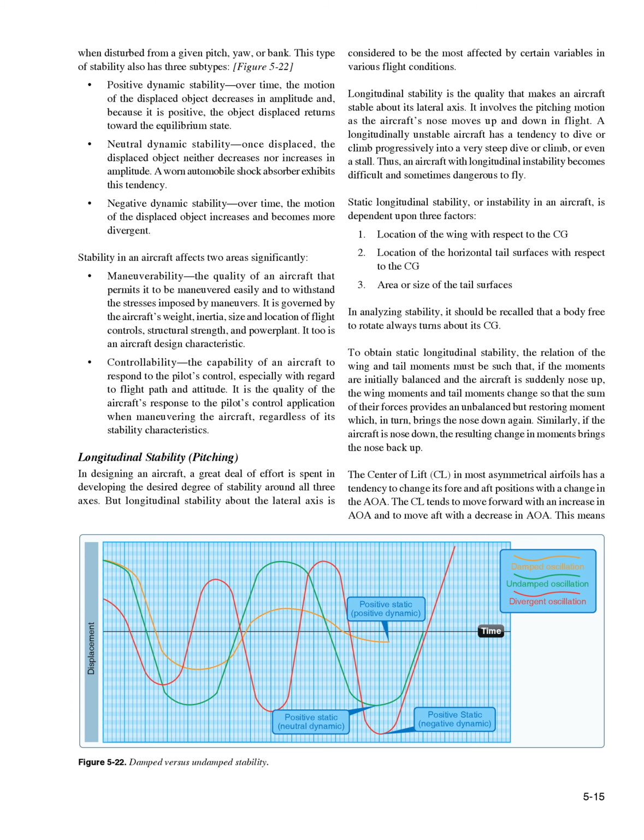Maneuverability, the quality of an aircraft that permits it to be maneuvered easily and to withstand the stresses imposed by maneuvers. It is governed by the aircraft's weight, inertia, size and location of flight controls, structural strength, and power plant. It too is an aircraft design characteristic. Controllability, the capability of an aircraft to respond to the pilot's control, especially with regard to flight path and attitude. It is the quality of the aircraft's response to the pilot's control application when maneuvering the aircraft, regardless of its stability characteristics.